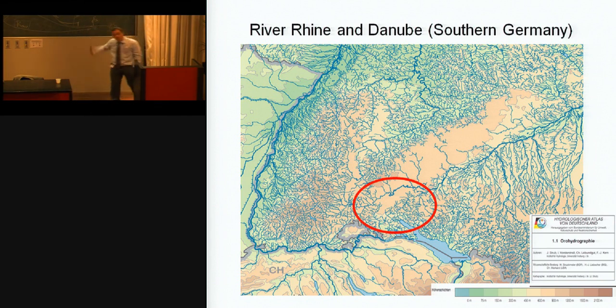Can you understand how difficult it is to make a proper water balance equation for this? Because the rainfall you can estimate. Let's assume you have enough rainfall stations, then you can estimate that rainfall. But then you don't know how much water actually goes into the subsurface and goes out in another catchment. And that's the challenge in hydrology, to get these boundaries right. Is that clear?